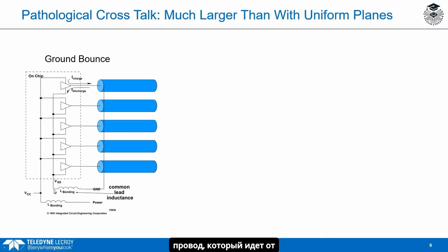And there's a lead that goes from the VSS on the die to the VSS on the board. And I'm assuming that the board has a nice wide plane. So there's very little inductance from the solder ball over here where the ball is, where the lead makes contact to the ground plane of the board. Here are transmission line paths going from each of the I/O to someplace else on the board. And we're going to turn these 4 on and off. We're going to switch these 4. We're going to keep the 5th one as a low. And so that means this output is connected over here.